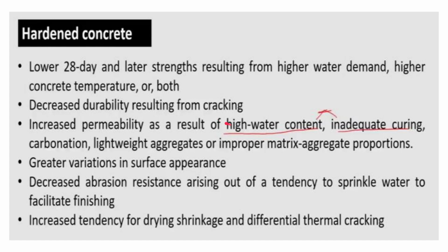The more the cracking, the more the permeability, and that will result in a larger ingress of chloride ions, which will result in corrosion. So increased permeability as a result of high water content, inadequate curing, carbonation, lightweight aggregates, or improper matrix aggregate proportions. Greater variations in surface appearance due to crack formation, decreased abrasion resistance also, because we will be sprinkling water to facilitate the finishing as the water gets evaporated, and there will be increased tendency for drying shrinkage.